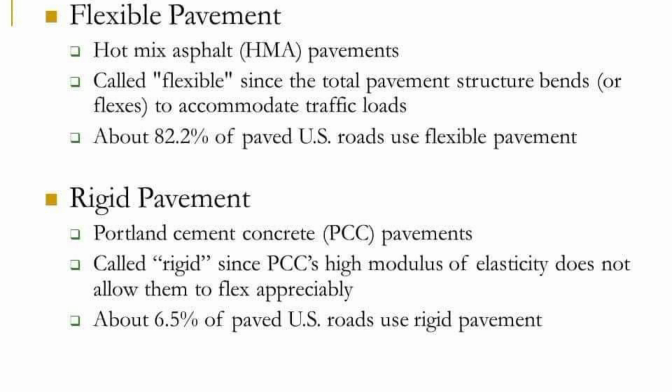The same condition we can see in the case of bridges as well. On the other hand, the rigid pavements are the pavements in which cement or ordinary Portland cement is used as a binder. This type of road have higher life as compared to the flexible pavements, but of course the initial cost is also much higher as compared to the flexible pavement.